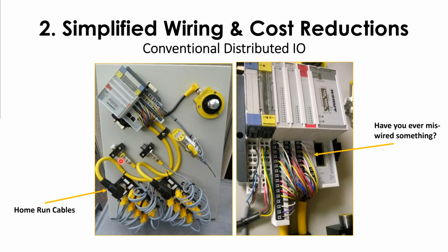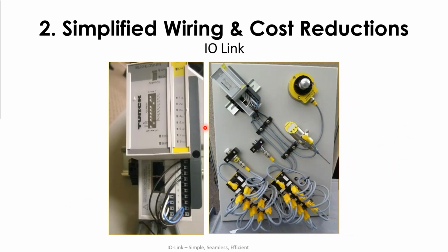You'll notice on the gateway here at the I/O rack, we're taking up multiple modules, so we have enough discrete I/O, we have an analog, and we have an SSI for this, and then of course there's landing the wires. Pretty clean historically. But now what we can do is, instead of using an SSI encoder, which you use because it has a lot of resolution, now we have an IO-Link encoder, so it's the same package, same technology, just a different reporting format.